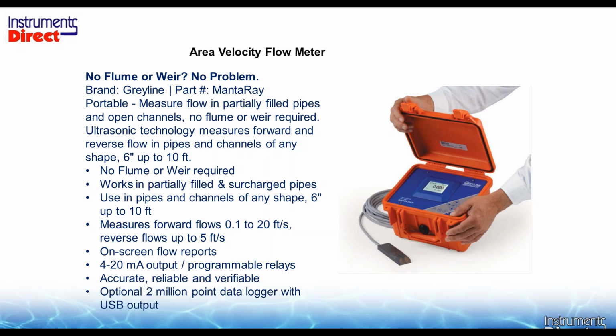And if we have an exotic application, you can actually put a level sensor that looks down from the top. So there are unique variations of this technology, but you can get it as a portable device. In this case, you're going to come with a battery-powered device that you put this sensor in some type of a mounting ring and shove that in the end of a discharge pipe. This part here in the front is the velocity. This part in the back is a level sensor.